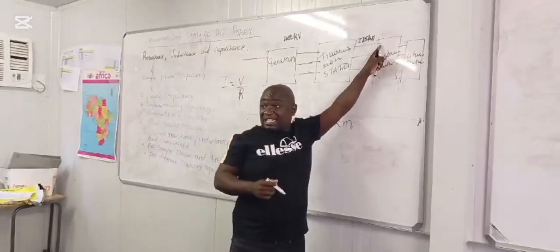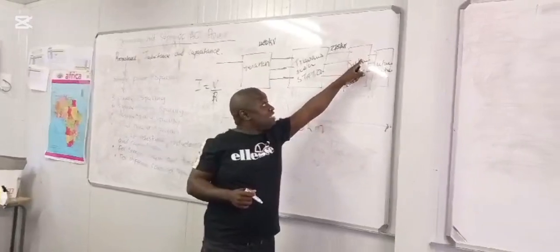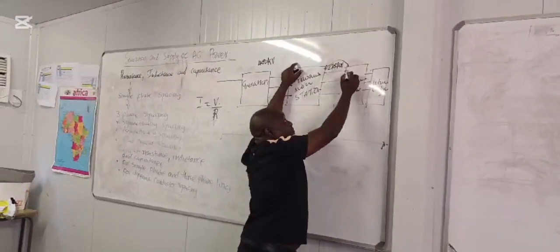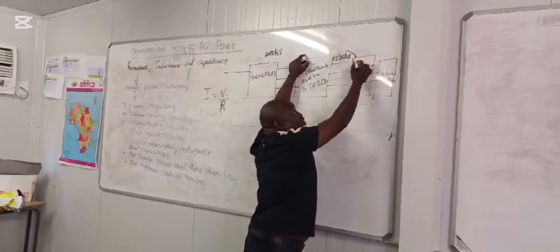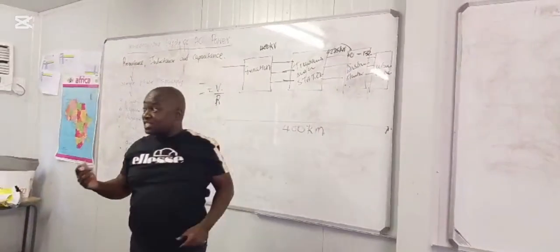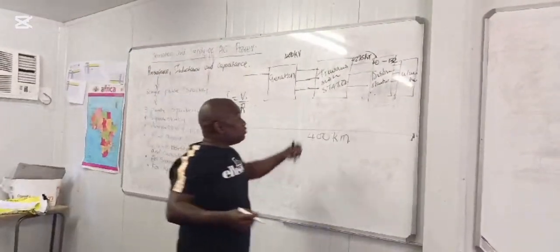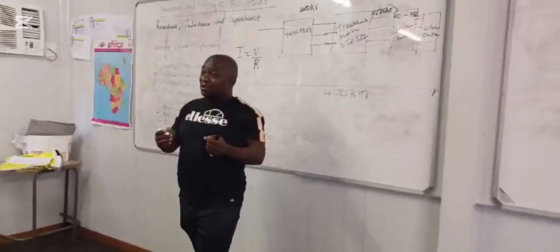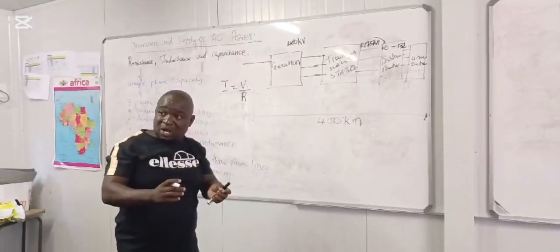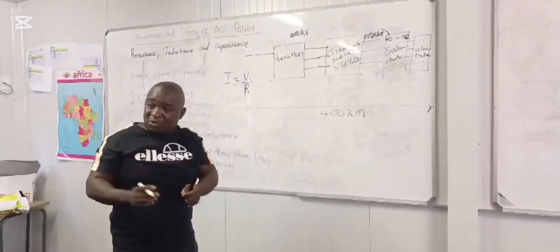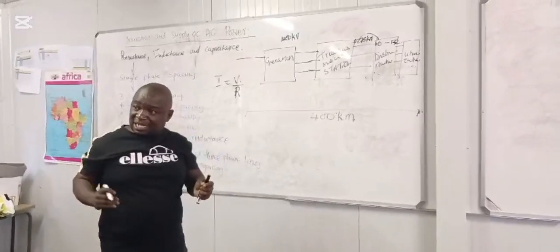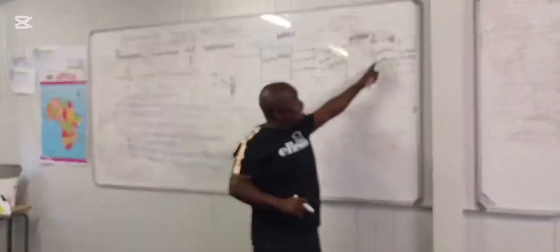From this 275 kV, over a longer distance from the transmission station to the distribution station, it comes in with 275 and can then be distributed from 275 to 132 kV on the distribution system. Are we together? Now in this case here, what we also notice is that as we are moving away from the generating plant, coming towards our supplier or our consumer, what is happening to the voltage? The voltage keeps on doing what? Reducing. Are we together?